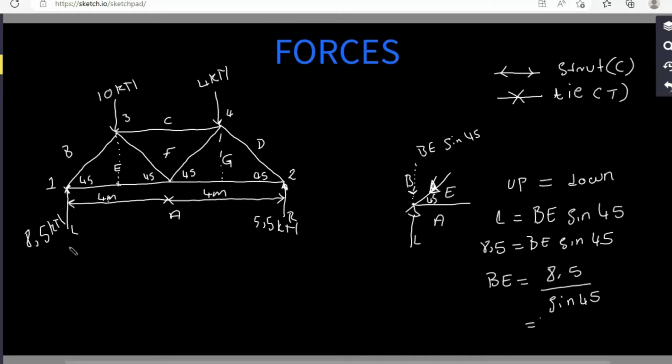And the answer that we are going to get here is 2.021 kilonewtons. The answer that we got is positive. That tells us that the direction that we have chosen is correct. If you choose a direction, you do calculations and then you get a negative answer, the answer is correct, but the direction is not correct.